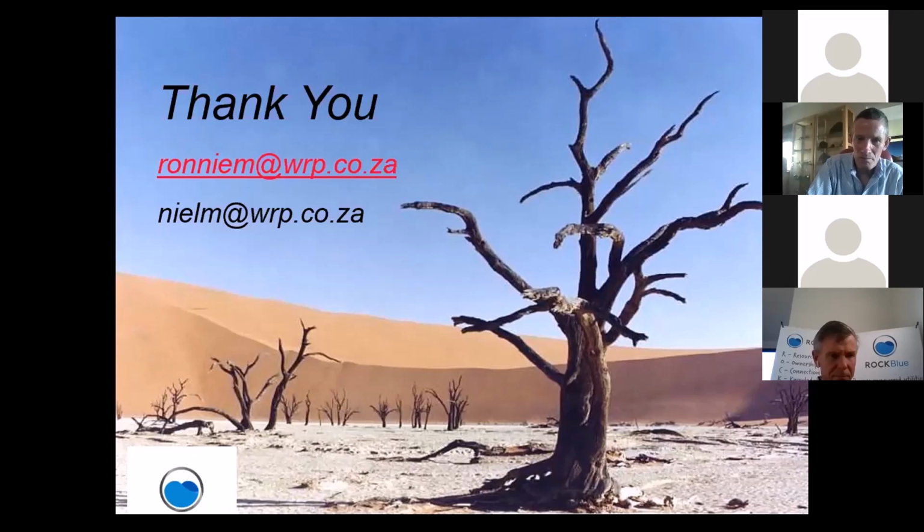Our next question for Ronnie is whether the nature of soil conditions can cause leakages. Definitely, absolutely. You will often find that, especially in areas that have got clay, the clay will move. During the dry season it will shrink a bit, and during the wet season it will expand, and that type of movement will create problems in any reticulation system.